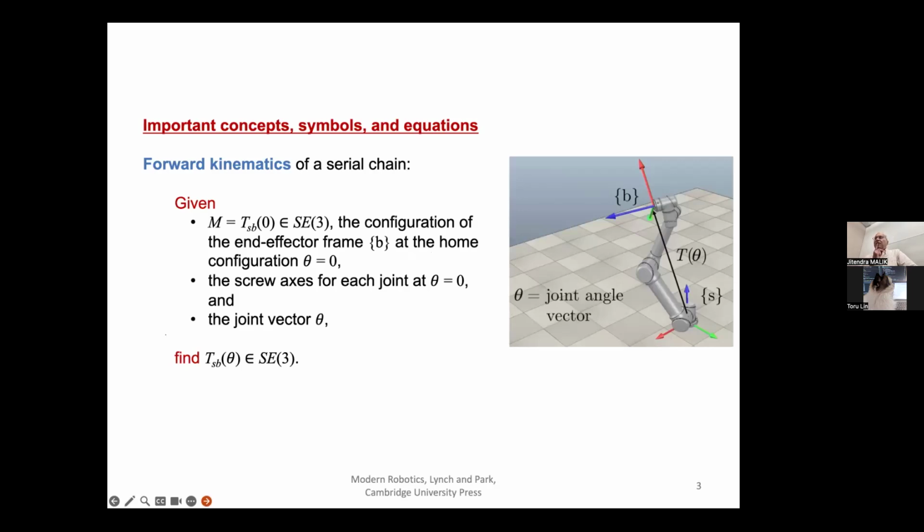First of all, going back some lectures ago, maybe in the second lecture, we talked about robot kinematics. This is essentially about the geometry of the system. You have a frame at the base of the robot or somewhere in the room, which is called the S frame. Then there is a B frame, which is the body frame, somewhere on the robot. What we know is the geometry: the lengths of every link, and the joint angles.